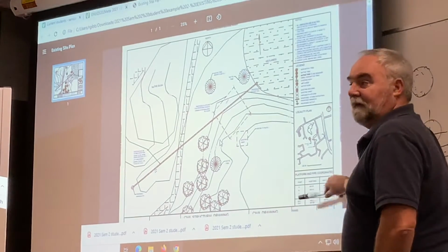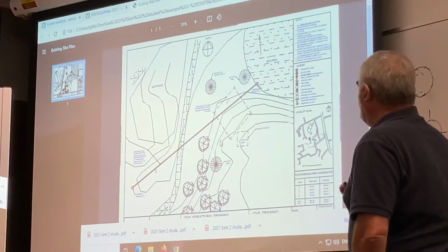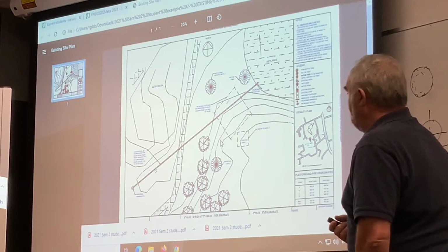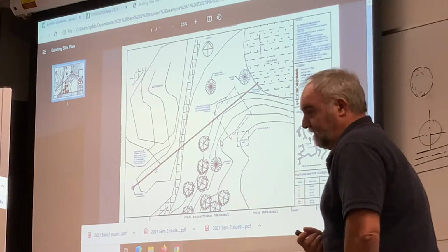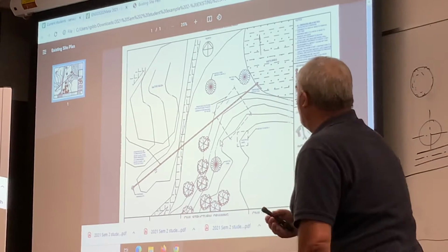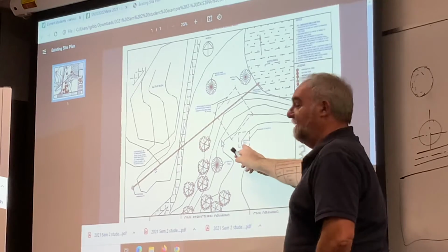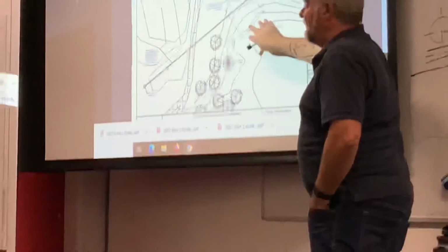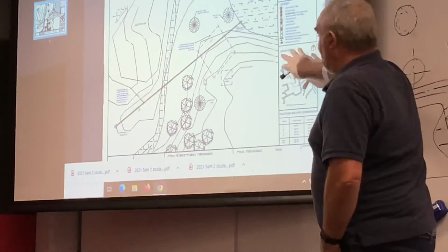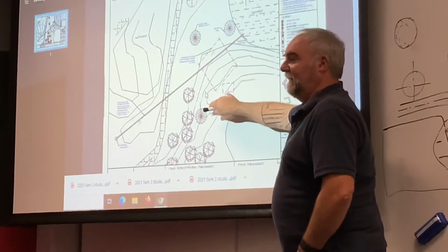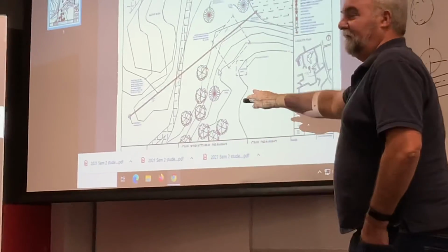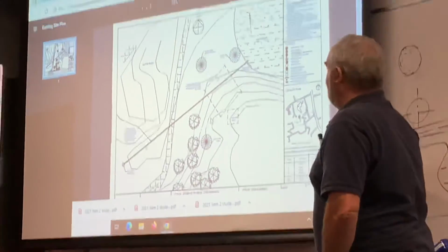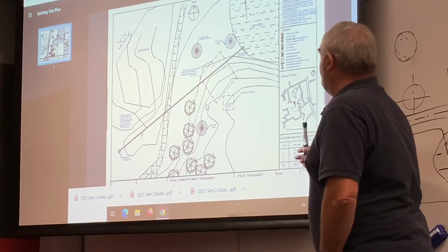All of that stuff there, the notes, the legend, locality plan. Is that in your model space, or is that... Yes, it will be. It's in your model space. And I'm going to show you how to do it so you can maintain the same text type. So obviously, if that's a viewport with 1 to 100, if you make that a viewport of 1 to 100, then you can use the same text type, and it'll all come through nice, readable type. And you're wondering how I do it? Well, we'll do that shortly.